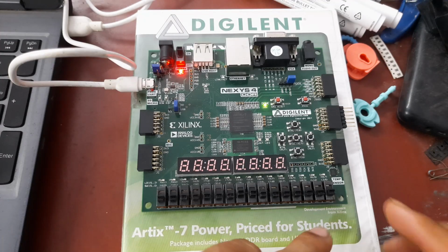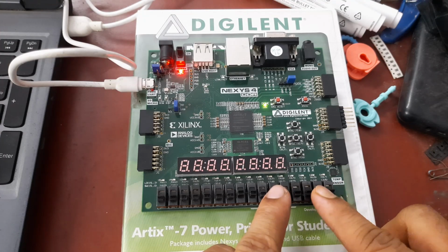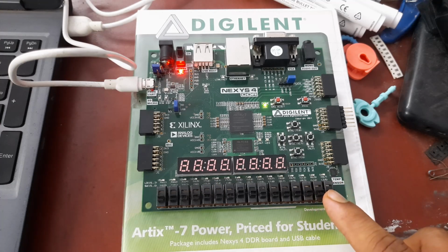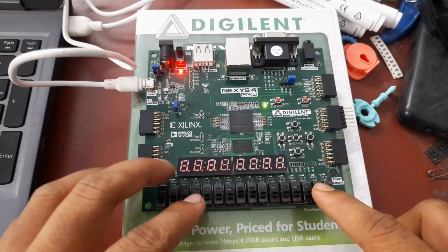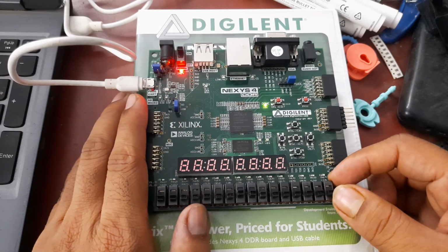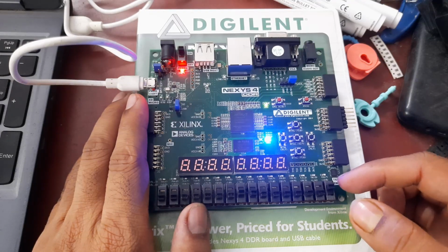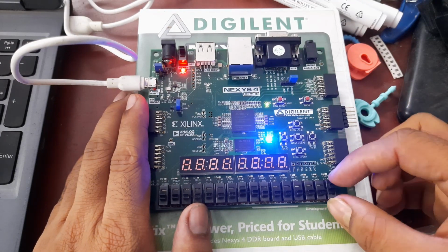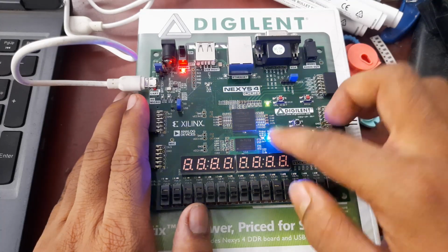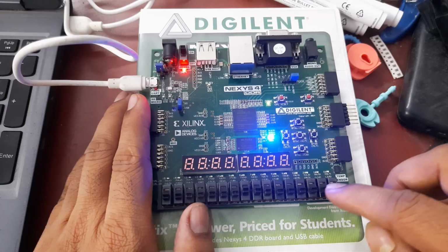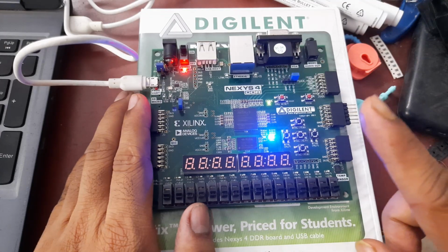Now it's programmed. Okay, so this is S and this is R, I think. Let me check the constraints. This is S and this is R, right? And okay, the LED is again the same. So when I set the flip-flop here, as you can see, set is high, LED becomes high, and when I do set as low, LED remains as high, right? This is SR flip-flop. I have both S and R as 0, so LED should remain in the previous condition only.